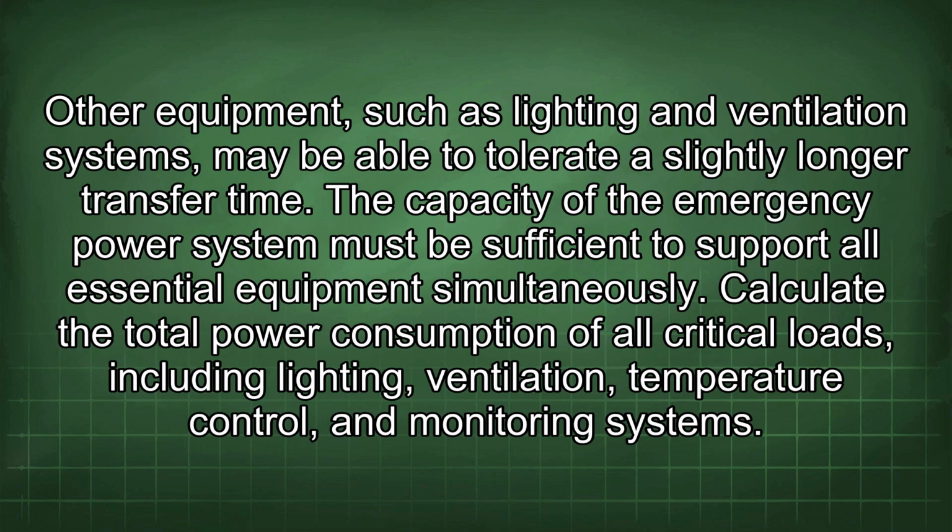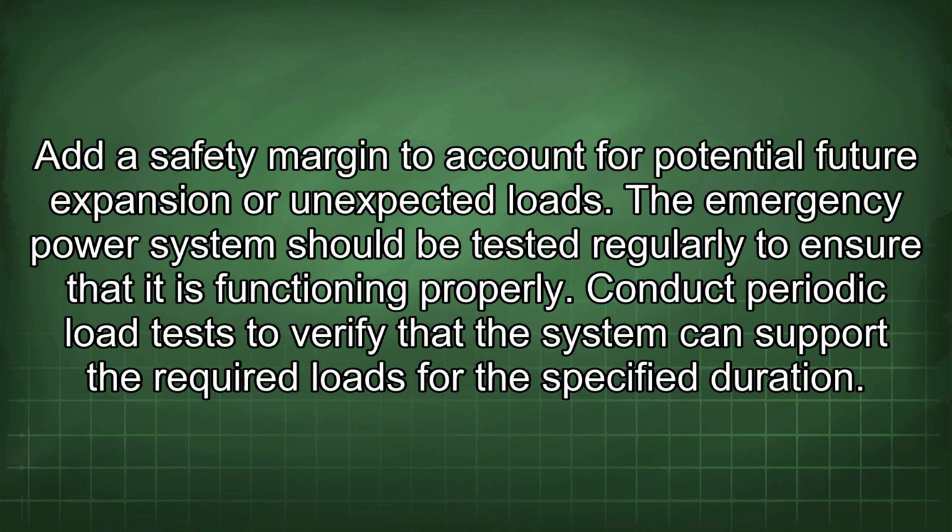Calculate the total power consumption of all critical loads, including lighting, ventilation, temperature control, and monitoring systems, and add a safety margin to account for potential future expansion or unexpected loads.